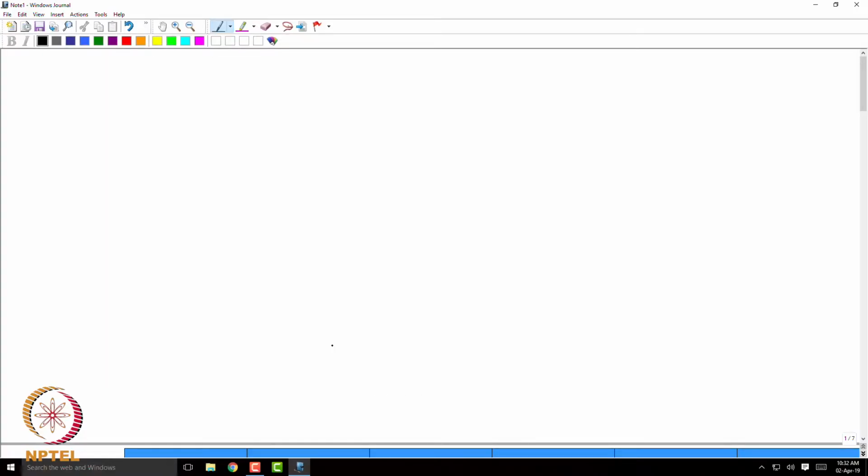Okay, so we are looking at turbulent flow in the pipe. That's what you just did, in fact, right? We calculated V average divided by V max, which is what is in the numerator, V average. V average by V max is equal to 1 divided by 1 plus 1.3 square root of f.